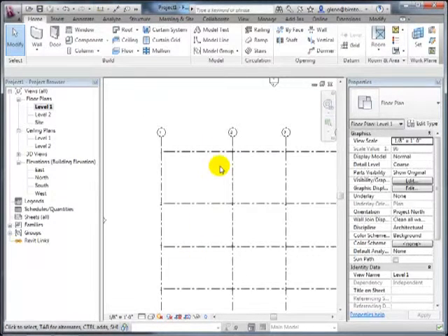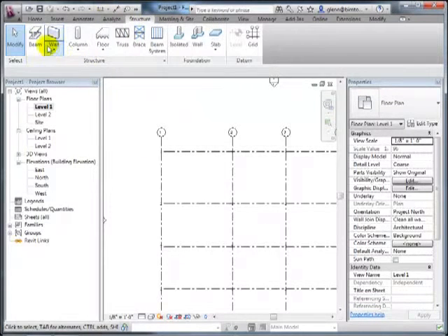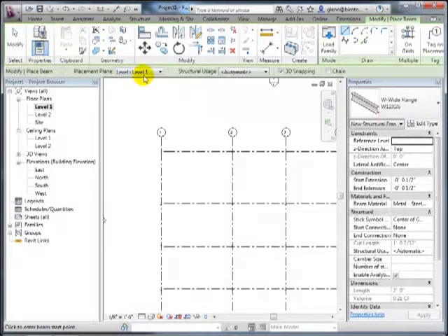Okay. I have my basic columns down here. What a lot of people will do next is start adding beams to the column and then joists to those. And there's really a very logical progression to the whole thing, where you can, again, either do it in the 2D view or you can do it in the 3D view. You kind of get to choose which way, or both. If I do it in the 2D view, again, here's what to watch out for. As you place your beams, watch out what level they're going to come onto. I'm going to say level 2.